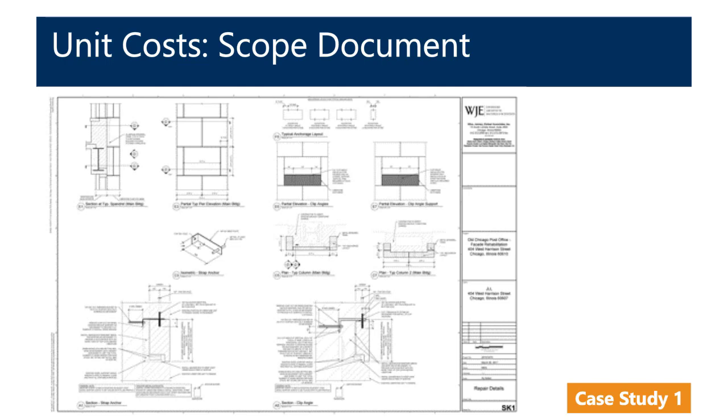Saw that the majority of the stress was occurring at shelf angles, so kind of a typical location. Able, based upon experience, knowledge, and a little bit of documentation of how the building was constructed, to come up with a repair design. And this sheet is one of a couple. It gives a typical idea of the intent of a limestone repair. It gives the size of the unit, but not only that, it gives a number of anchors and things to do to the structural support in the backup, clean and paint steel, things like that.